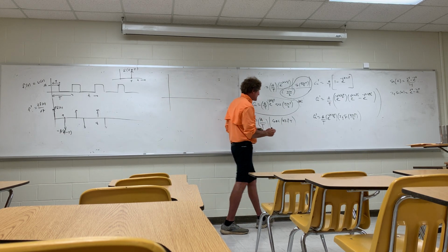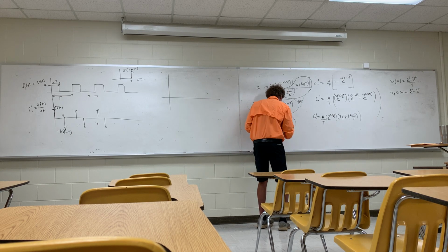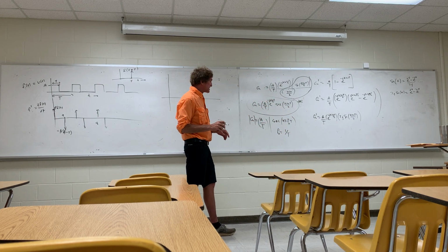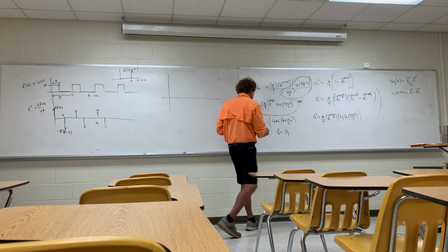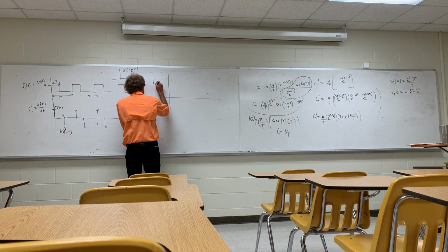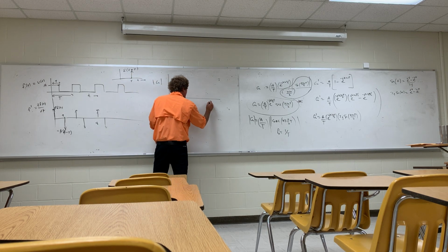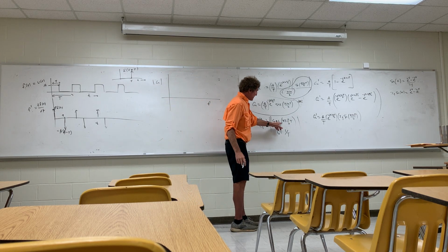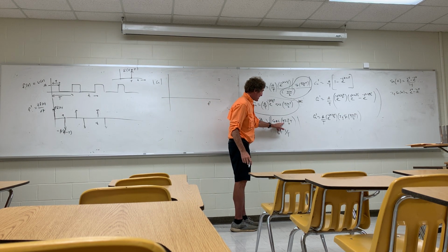So remember, f naught, which is the fundamental, is simply equal to 1 over the period. Follow me on that, class? Now, the reason I did it is this. When I look at the magnitude of C of n versus f, what I can see is that as I increment n, I'm really sampling the sinc function's envelope at different values. Now just follow me on this.